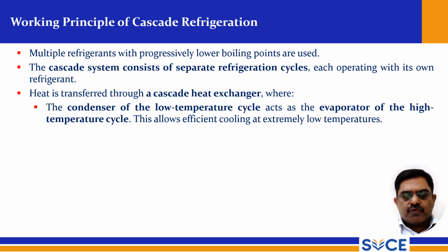The condenser of the low temperature cycle, that is the LT cycle, acts as the evaporator of the high temperature cycle. For the high temperature cycle, it acts as the evaporator. This allows efficient cooling at extremely low temperatures.